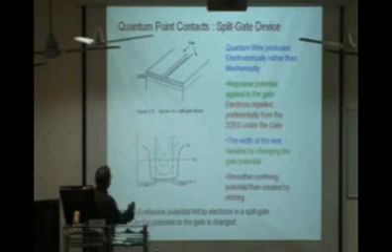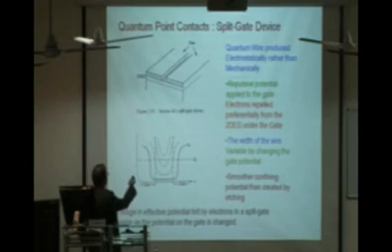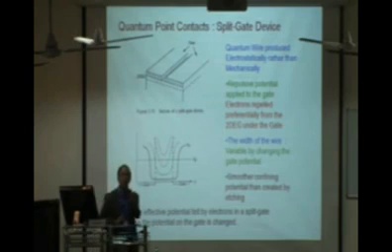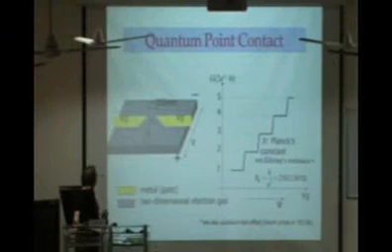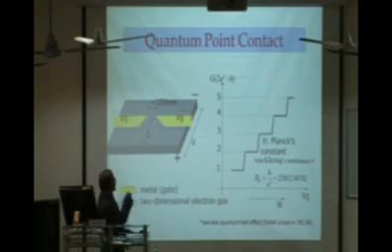As you see, when the gate voltage is very low, the depletion width is very small. But as we increase the gate voltage, the depletion extends into the region where there is no gate, and ultimately at some point, just before the overlapping, they give a very narrow region which behaves like a quantum wire. This is called a quantum point contact device. In fact, people have already demonstrated by electron beam lithography that if you make a MOSFET with a two-dimensional electron gas and put two gates very close to each other, with a separation in this case of about 250 nanometer, which could be achieved easily by electron beam lithography.